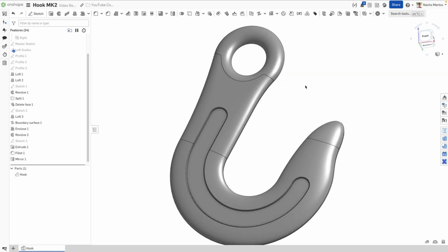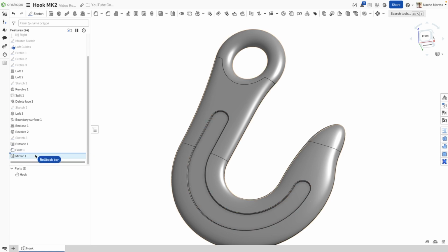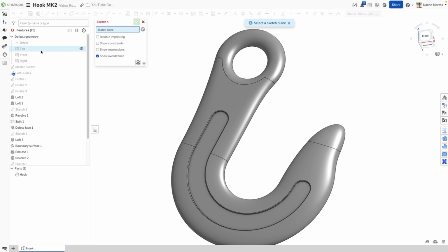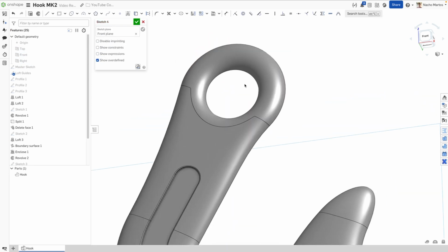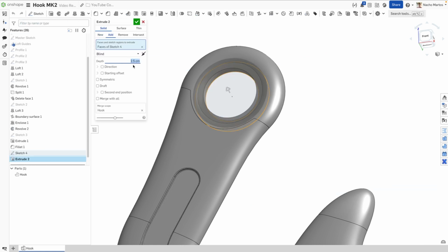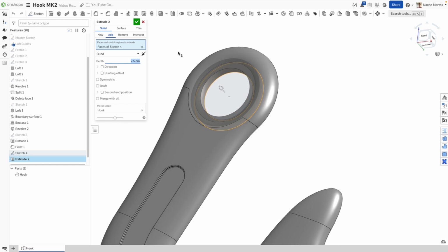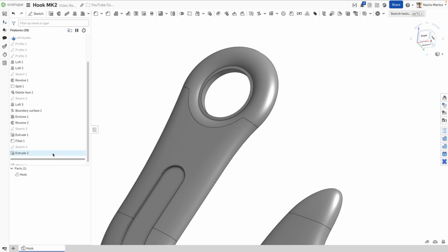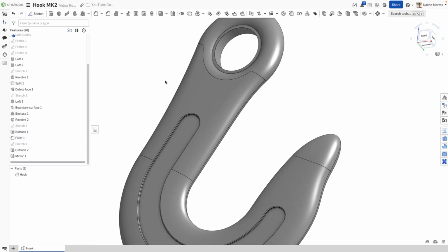and ready to go. If we wanted to do some last detailing, we might want to add a little bit of detail here, for where our contact points are going to be, and you can customize this however you want later. So we're just going to do a little offset of this geometry. Maybe we'll do 3 centimeters, and then we're going to extrude that out around 2 centimeters, 2.5 centimeters. Looks to be a good amount, and from here we can just roll that right to the end. And now we have our hook.